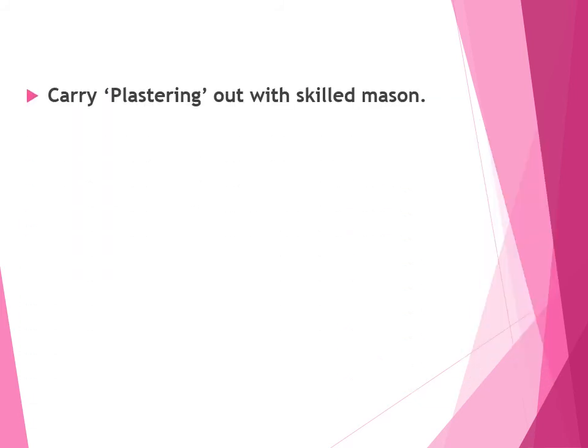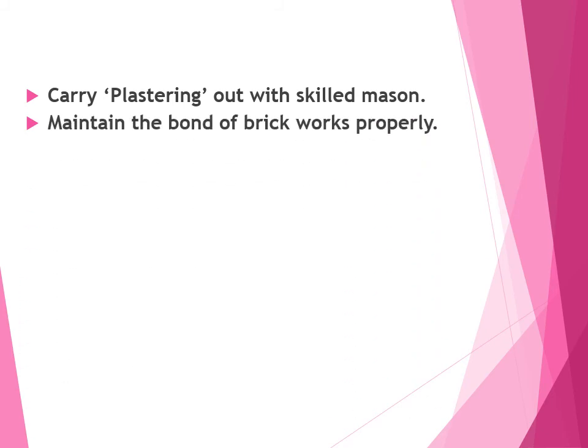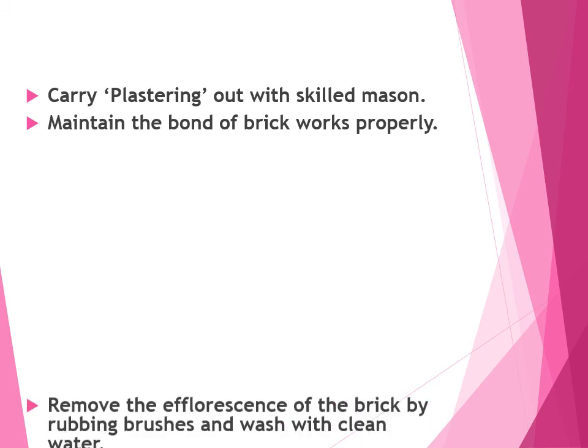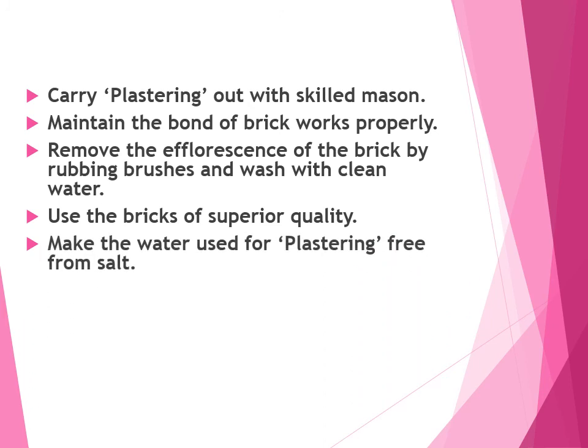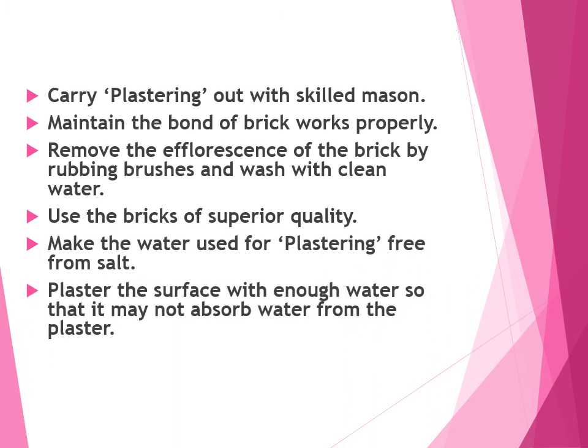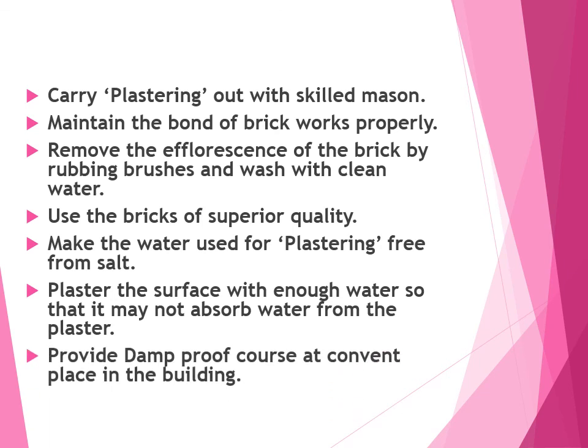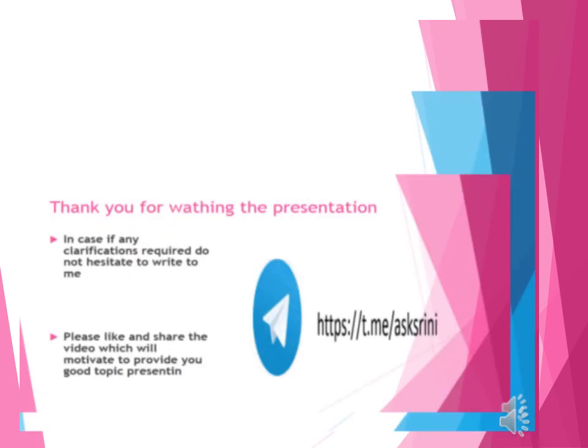Carry out plastering only with skilled personnel. Maintain the bond of the brickwork properly. Remove the efflorescence of the brick by rubbing with brushes and wash with clean water. Use bricks of superior quality. Make the water used for plastering free from salt. Wet the surface with enough water so that it may not absorb water from the plaster. Provide DPC at convenient places in the brick.